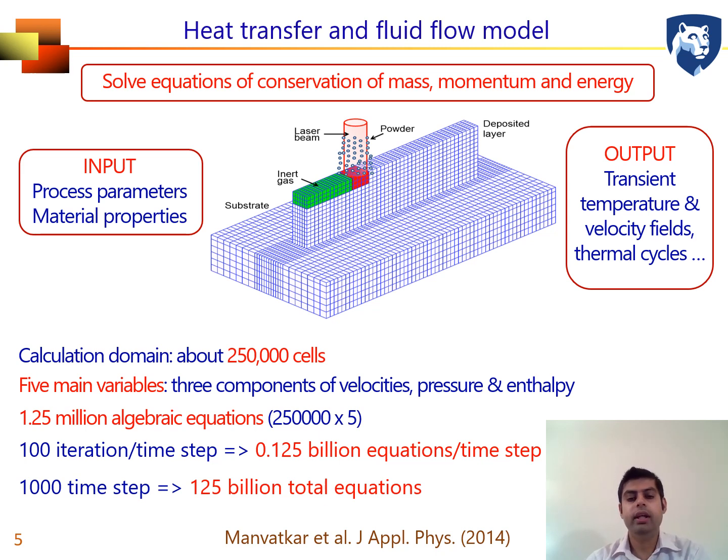And to simulate the continuous movement of the laser beam, we discretize the entire time into small time steps, let's say 1000 time steps. So as a whole, we are solving 125 billion equations. And on an inexpensive laptop, it takes just 10 minutes. After 10 minutes, you can get the temperature fields, velocity fields, thermal cycle, cooling rates, everything that you need.